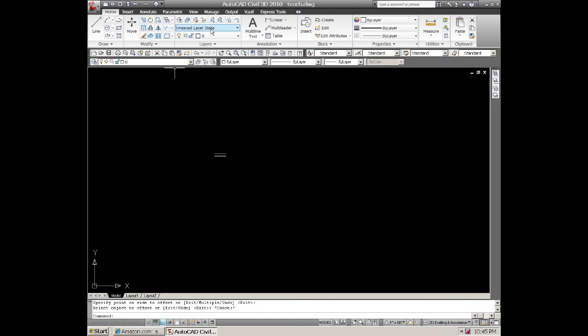Then we're moving right along. This is our layers. Again, advanced stuff. If you don't know your layers, you can click right here, which is the main thing to know what layer you're on, and you can change your layer as you go. Always make sure that you're on the right layer for the right thing that you're drawing, and do create layers if you get in the advanced stages for each object that you're doing. Don't put everything on layer 0. And there's some advanced things. The pull downs are mainly your advanced things.